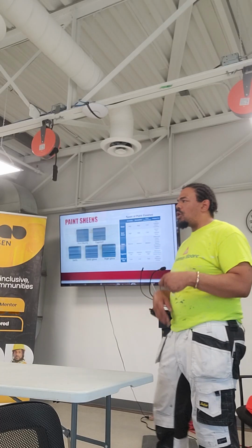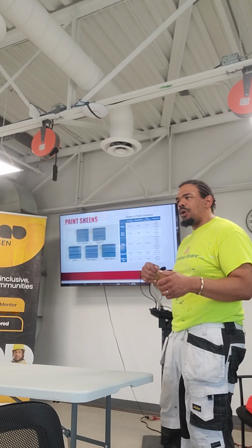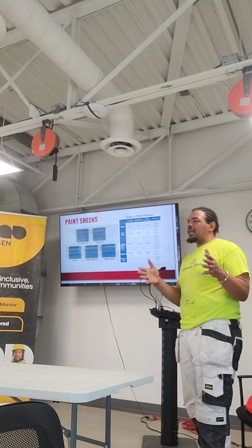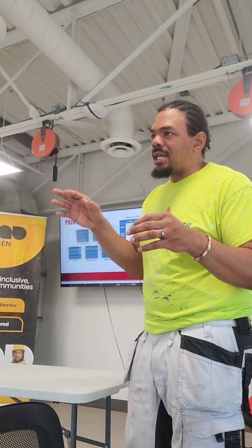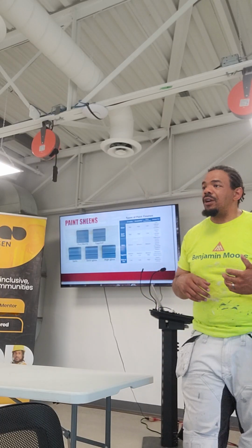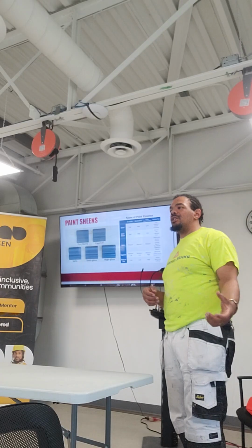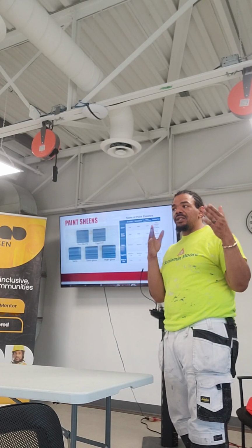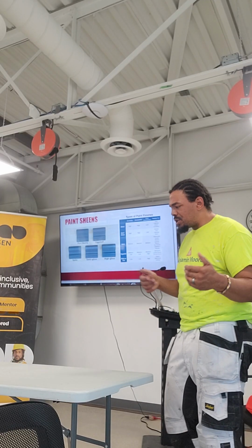You can make a whole bunch of mistakes, or do a whole bunch of dents and damage to a flat paint wall and then paint over it, and without doing any work, stand back and look at it and it looks perfect. Until you walk up on it and start inspecting and seeing all of the issues. So understanding how those things work is going to affect your finishes. That's why a lot of times you have to use a light to do an inspection for your touch-ups and your repairs on flat walls, because just to stand and look at it, you can't really see it. So you have to keep that in mind as you go through.